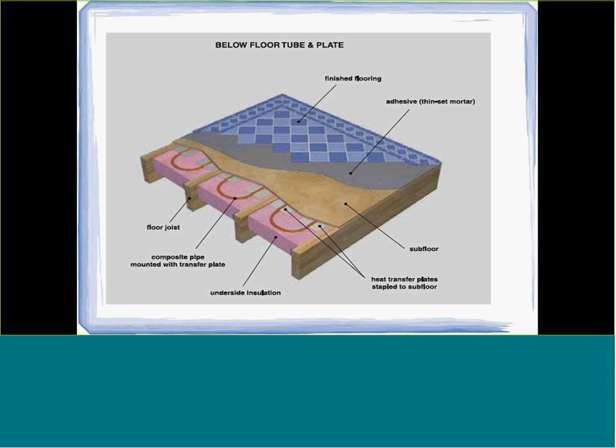And then a lot of times when people are remodeling, they can get to the floor from the basement and they want to do their first floor in radiant. If you can get to the floor joist, you can put tubing between the floor joists. And that tubing usually goes on 8-inch centers with a 16-inch center floor joist. And we always recommend using plates, especially if you're going into an older house where you may have extremely thick subfloors. Sometimes you'll actually have 2 subfloors.